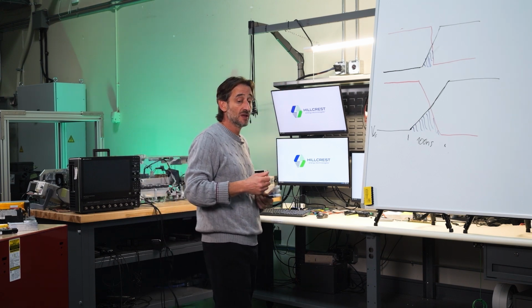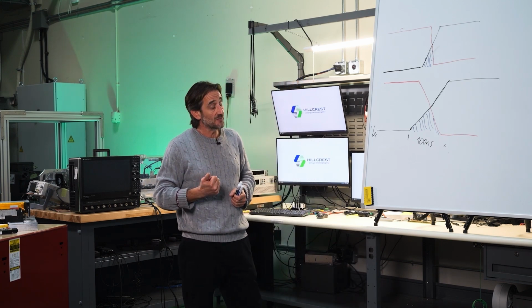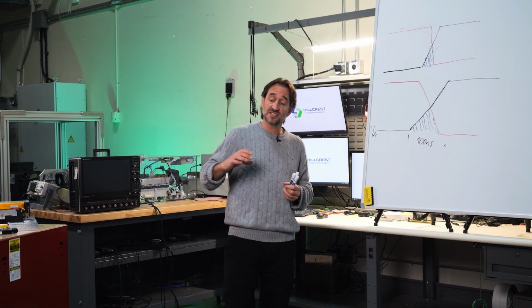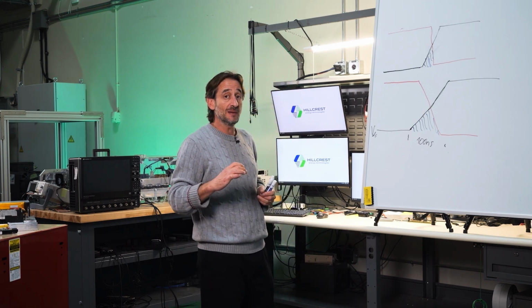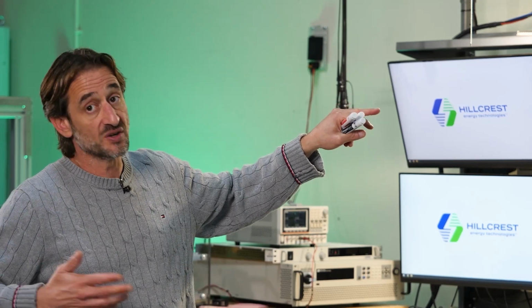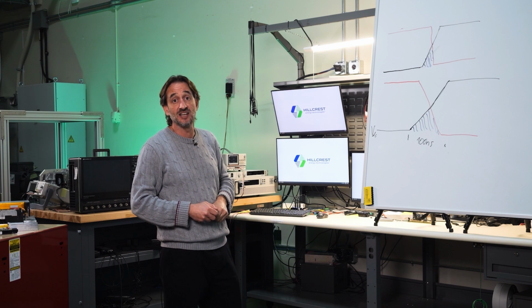For example, the insulation on motor windings. Some of them cannot withstand that high dV/dt. There is something called stray capacitance or parasitic capacitance because of the lines and just the layout of the whole system. That parasitic capacitance will react with parasitic current in the system due to this high transition.